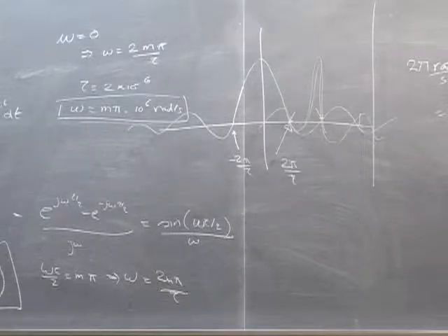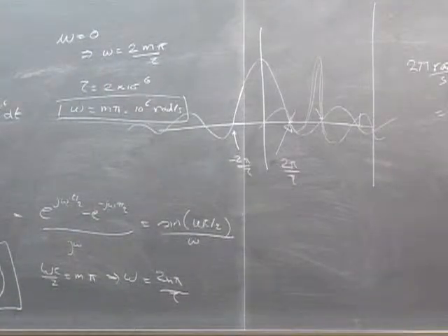And so generalizing this, and I'm going to wave my hands here, it is possible for us to come up with a set of frequencies such that pulses sent on these frequencies don't see each other. These particular frequencies are called orthogonal frequencies, and that's the basis of what's called orthogonal frequency division multiplexing. So instead of a carrier, we have what are called subcarriers. Typically you'll have 4, 8, 16 subcarriers, and in each subcarrier you'll put a different signal, and magically they don't see each other.